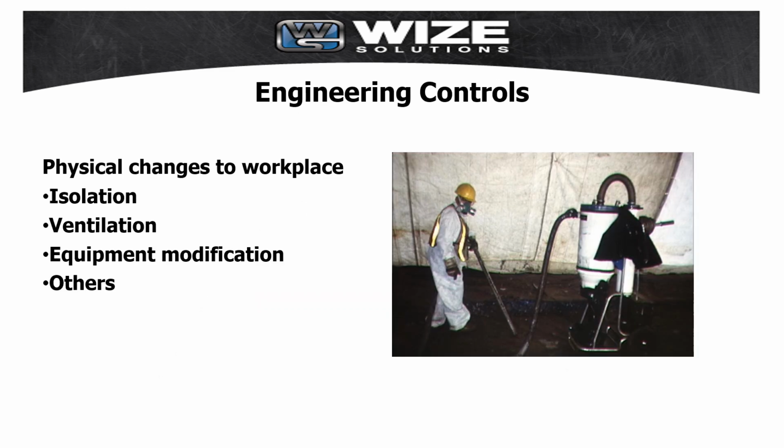Engineering controls require a physical change to the workplace based on the following principles, OSHA 2001. If feasible, design the facility, equipment, or process to remove the hazard. If removal is not feasible, enclose the hazard to prevent exposure in normal operations. Where complete enclosure is not feasible, establish barriers or local ventilation to reduce exposure to the hazard in normal operations.